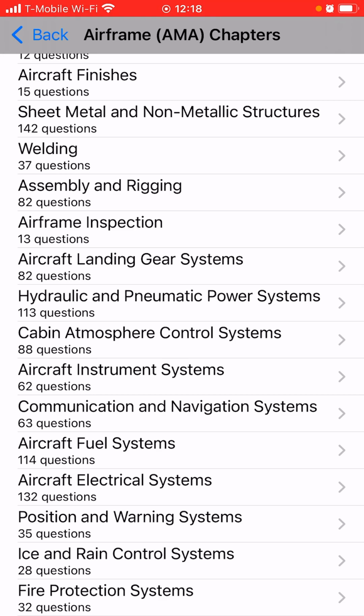So I'm going to say B. Metal fasteners used with carbon graphite composite structures must be constructed of material such as titanium or corrosion resistant steel.